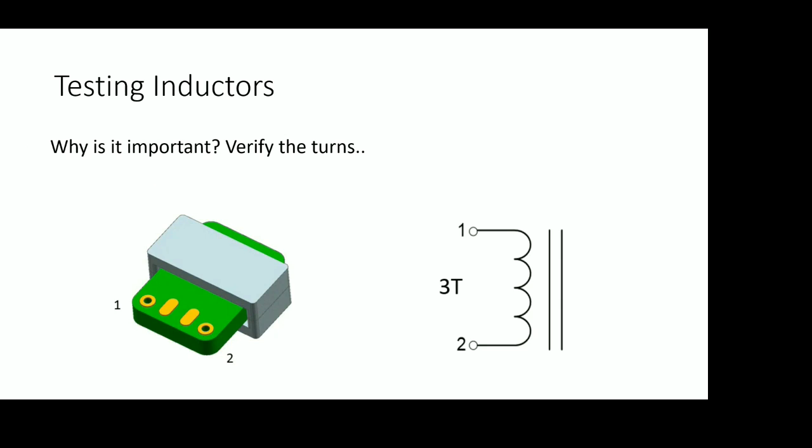And of course, with this type of test, because the coils are small and the leads of the copper wire are long, we need to see small changes in the measurement. So when we talk resistive or inductance, Henry, we're talking micro. So we have to ensure that we have 4-wire Kelvin probes on there. The 4-wire Kelvin probes make double contact on the pads to ensure that the meter readings are very precise.